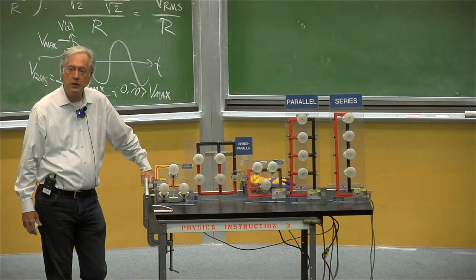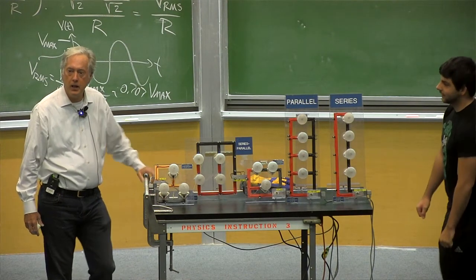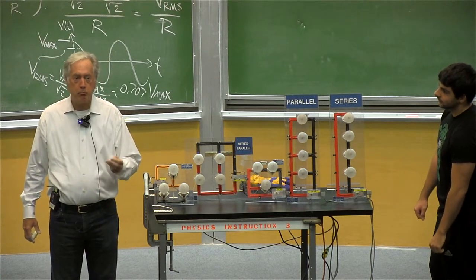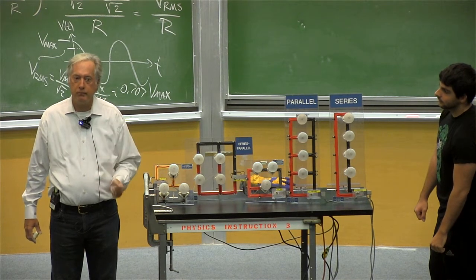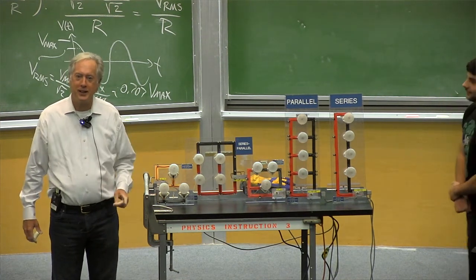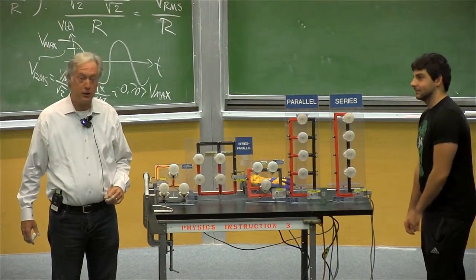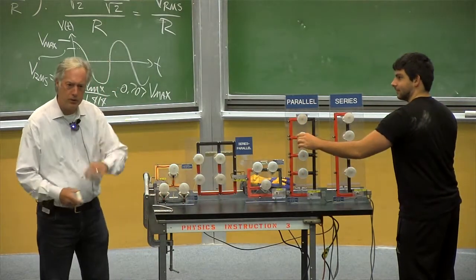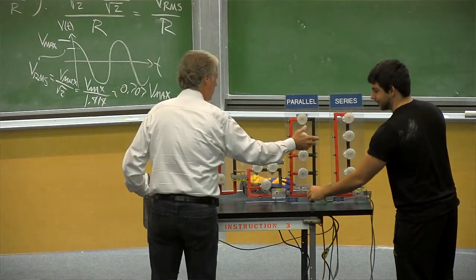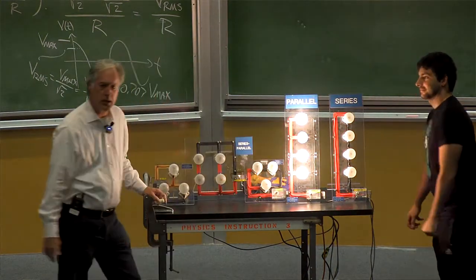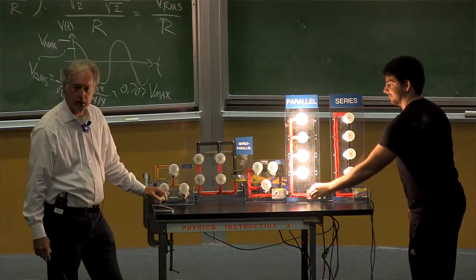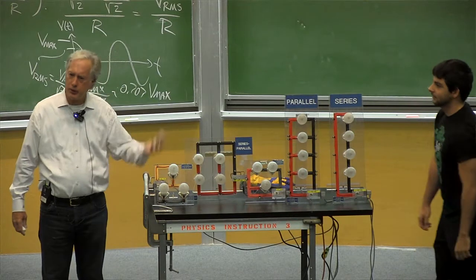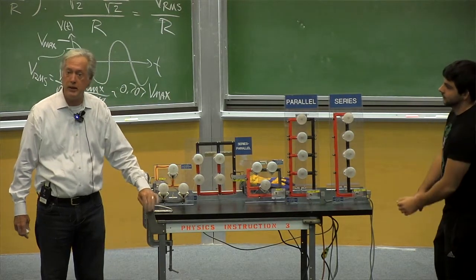One of them going open didn't affect the other three, did it? In particular, when one of them went open, did the other three get brighter? No, I don't think so. Let's try it again. We have one unscrewed. Let's measure it again. Turn them on. Did they get brighter or not? No. Okay, turn it off. Okay, screw it back in. And what was the approximate brightness telling you? Was that about 60 watts per bulb? That was about normal brightness, right?